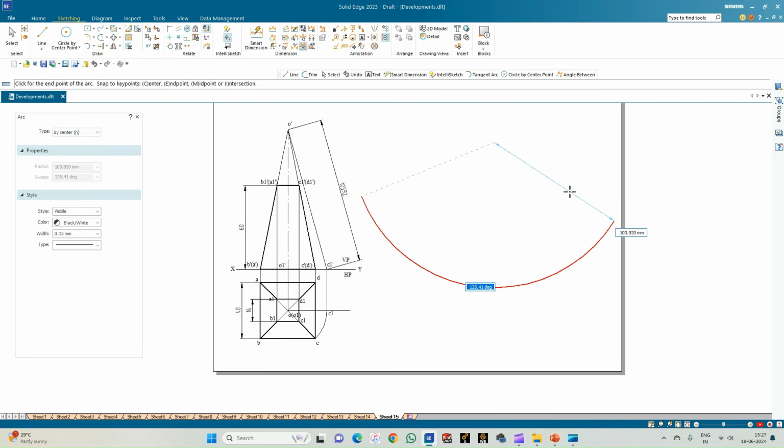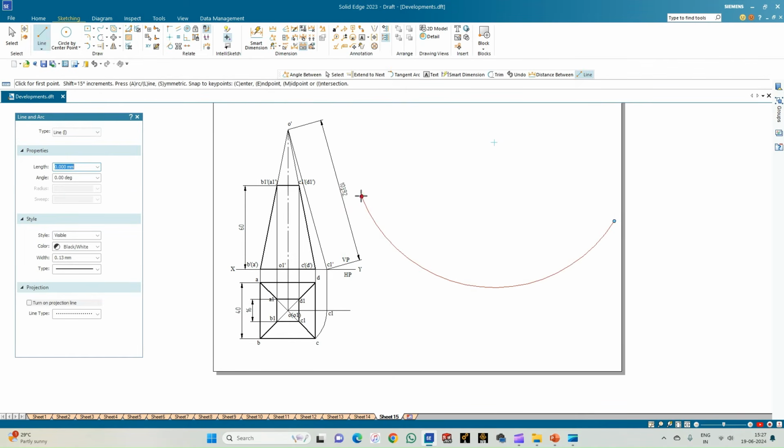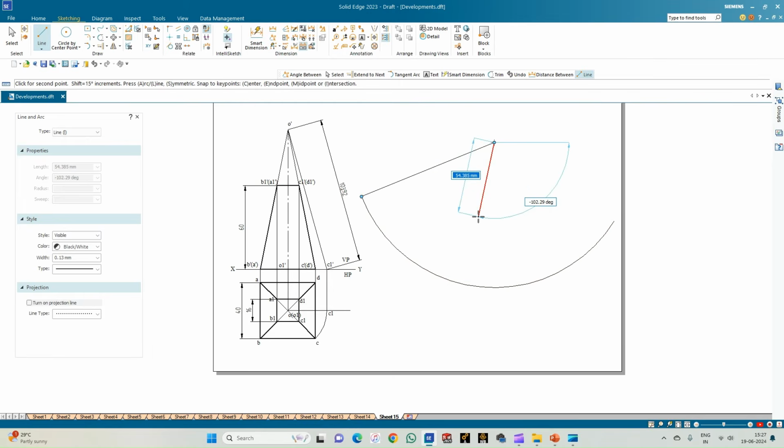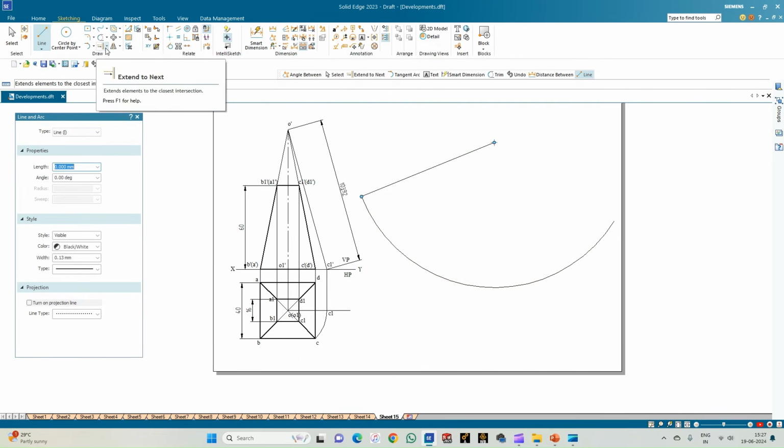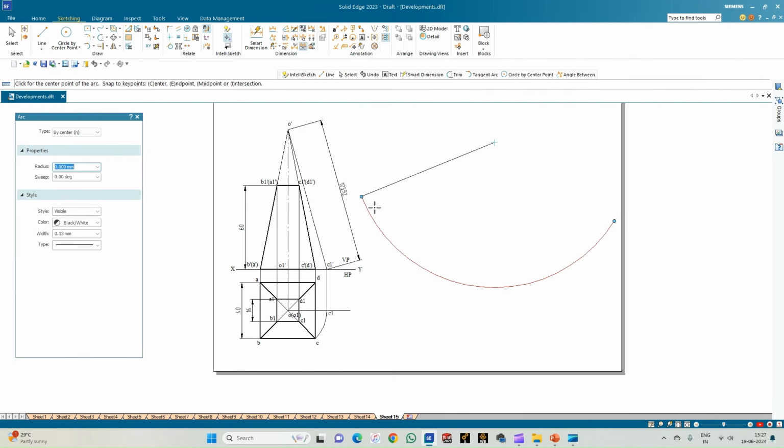So cut an arc and then connect one end of the arc with a straight line to the center point, and from that point you can take the reference and start cutting the arc which is having a radii which is equal to 40 mm. So just sweep 4 arcs so that you are dividing the arc into 4 equal parts. So since the square will be having 4 triangular faces, we'll be dividing this into 4 equal parts. 40 mm. So this completes the division.